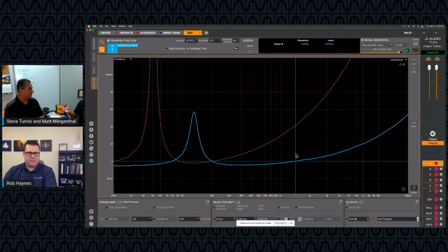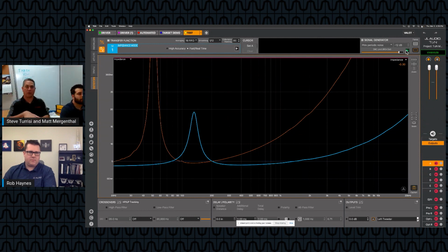You have anything else to share on that? What else can you do with impedance measurements? One thing I like to share with people, and we don't have time to get into all the details of this, but if you have a sealed enclosure with a subwoofer in it, if you want to check the resonance of the sealed box, it's no longer just the driver, it's the whole system. So you can take your impedance probe measurement at the terminal of the entire enclosure, and you can see the resonance of it. Similarly, if you have a ported enclosure, you can not only see the resonance of the box in that case, but you'll see the tuning frequency. Those impedance plots, as you go from low frequency to high frequency, you'll see a peak, then they'll come down, you'll see a valley and another peak, and then they'll taper down and do some other stuff at the top end.